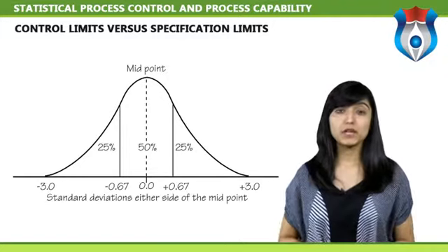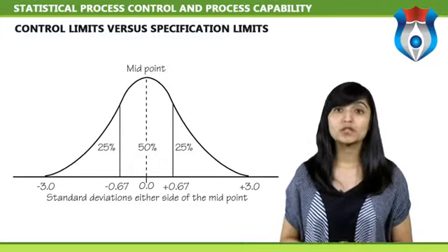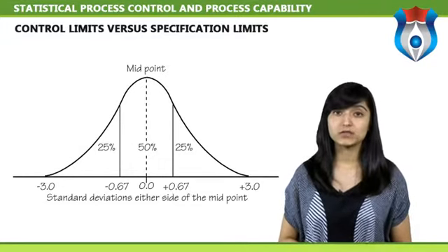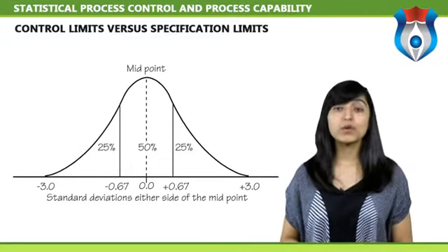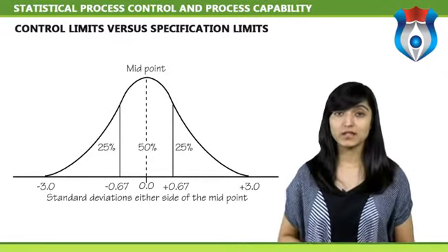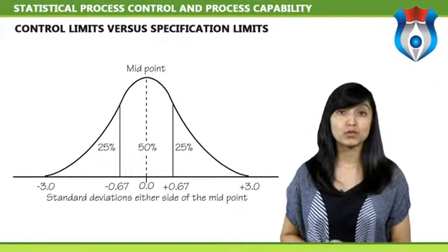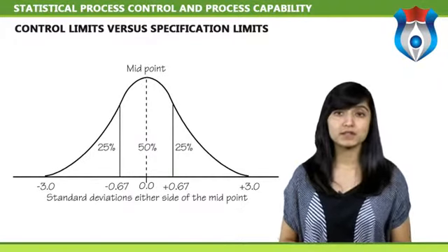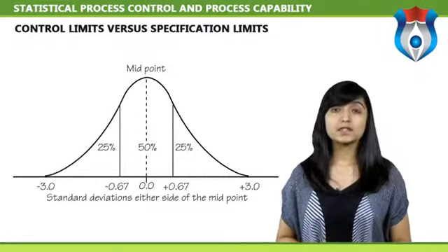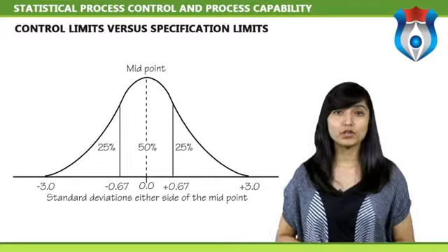For example, if we are filling cereal boxes, our nominal is the net weight printed on the box. We do not want to give away free cereal. But on the other hand, we know variation is everywhere. And if we aim for that net weight, we are likely to get some boxes under the marked amount, which can lead to substantial fines. In that case, our process target is higher than nominal so that we do not have any boxes under the net weight.